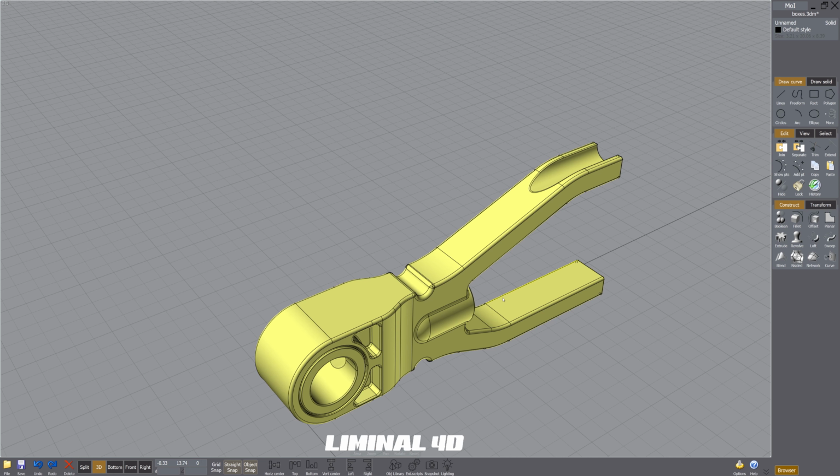All right, hey, quick one. Next video coming out is going to look at export settings for moving a model from Moai 3D to, say, Blender. The settings that we've used right now is for 3D printing. You don't want to export a model this way if you're going to Blender or Maya or Modo, because you don't want to work with triangles. It's unusable without retopology. So the settings that I'm going to show you next time is going to look at maintaining quads and reducing any kind of rework that you would have to do, so you can just export it over.